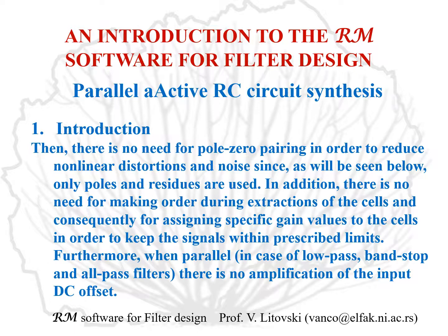In addition, there is no need for making order during extraction of the cells and consequently for assigning specific gain values to the cells in order to keep the signals within the prescribed limits. Furthermore, in case of low pass, band pass, and all pass filters, there is no amplification of the input DC offset.